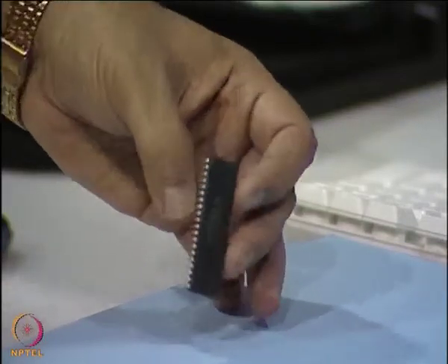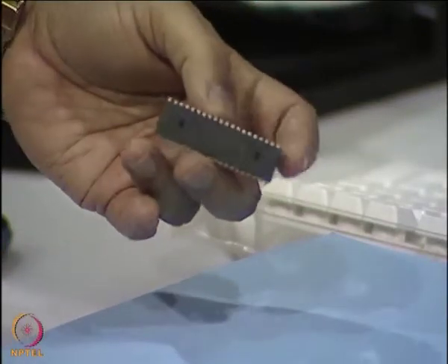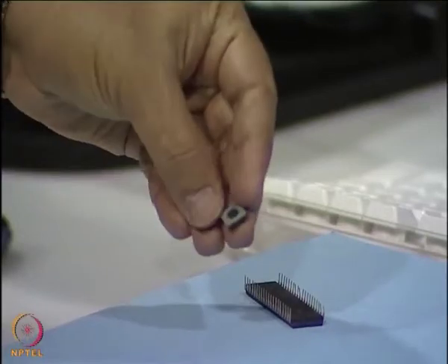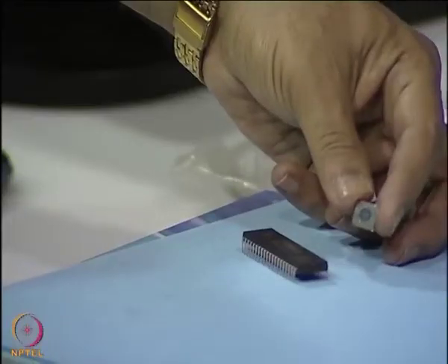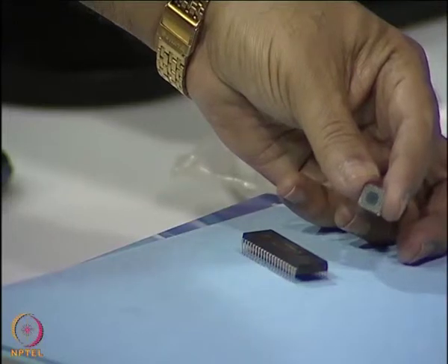This is known as a DIP package, dual inline package, and from here we have moved on to various form factors, and what I can show here is a very small device which probably houses 20 times this IC, functionally and with high reliability. Okay, this is a very large DIP package, whereas this is a small package. This is called a chip size package, which is equal to 20 times this particular package. How is it achieved? Because there is a lot of miniaturization from the design stage.